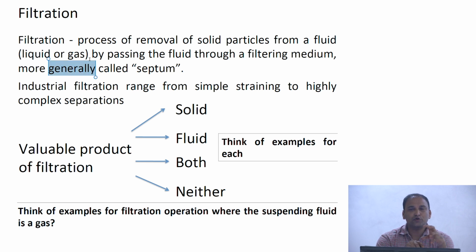For you to separate out the solids, you would have to pass this through a filter medium, which is also called a septum. That means you have some medium that has the capability of retaining solids. You have a fluid that contains particles, and you pass it through this medium, and ultimately the particles get deposited on the medium and the clear fluid comes out. That's what is done in filtration.